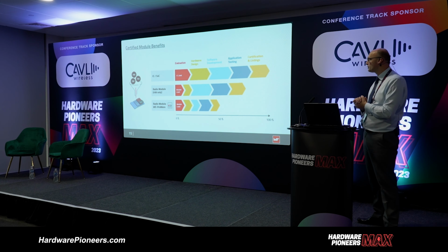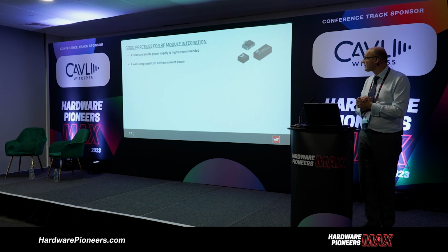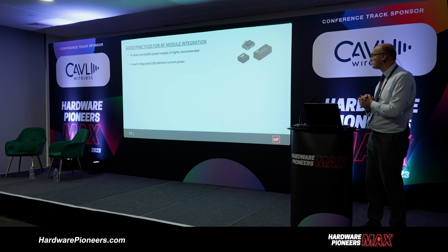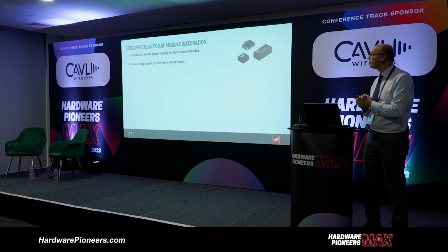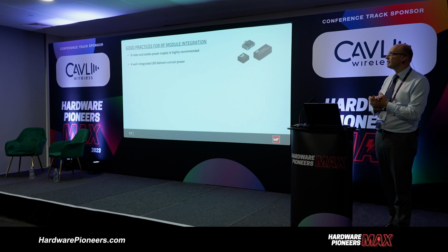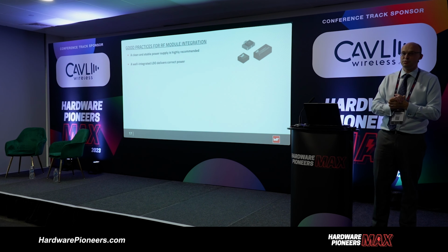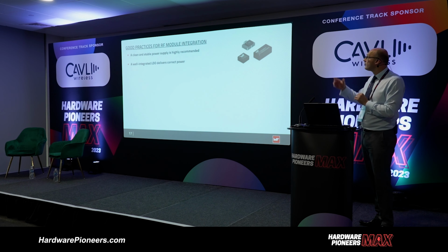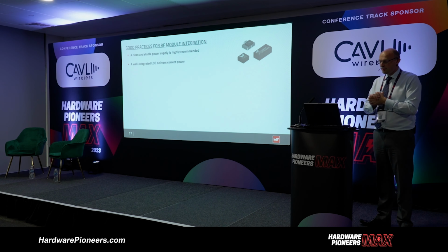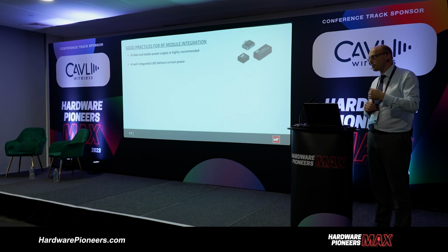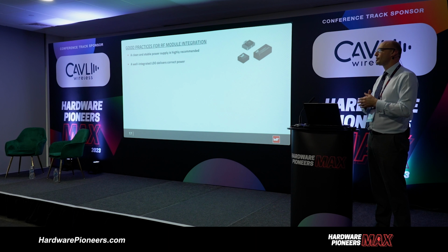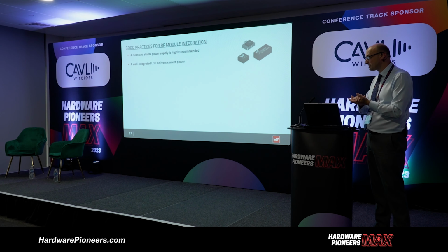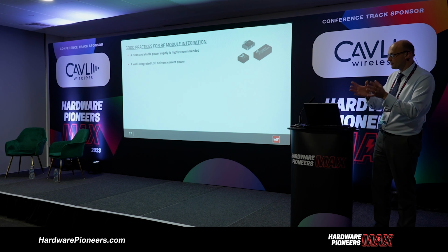So, good practices for RF module integration. Now I've mentioned you can take a pre-approved RF module. Firstly, they do need a very clean power supply. Why do I say a clean power supply? Once again, you're trying to replicate what we've had on our eval board that the module's been sat on while we've done our approval testing.